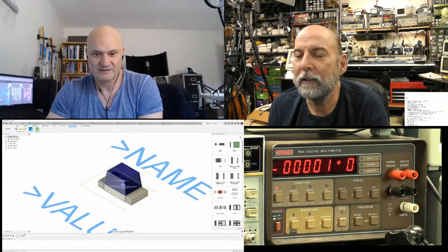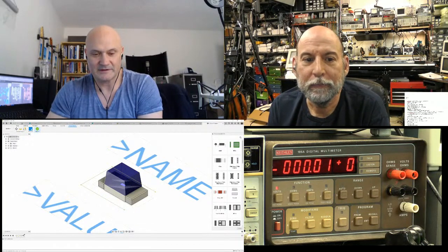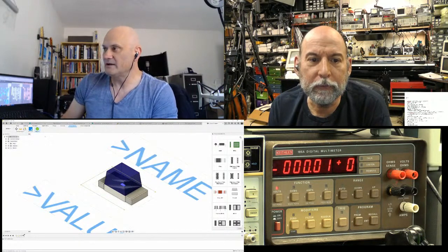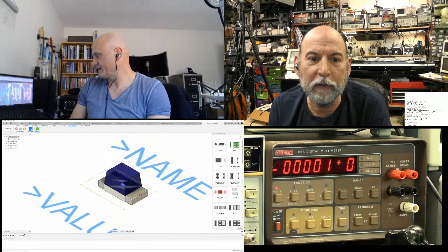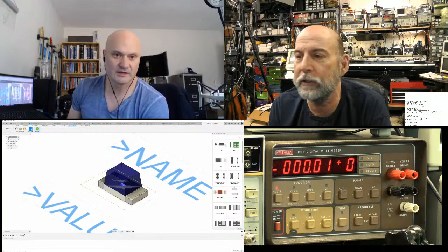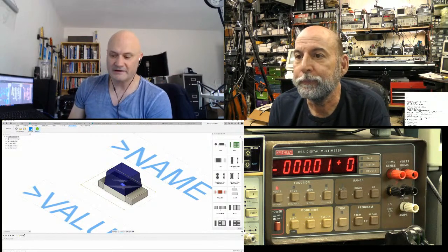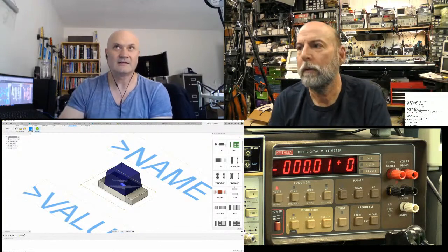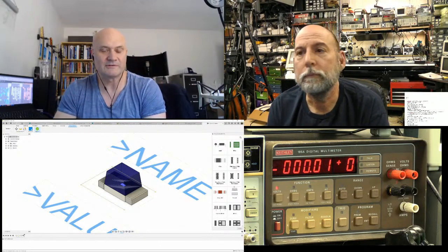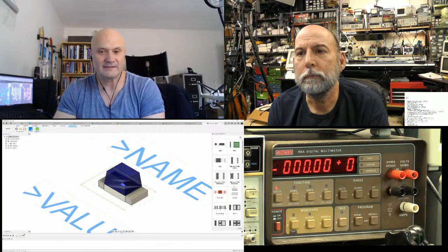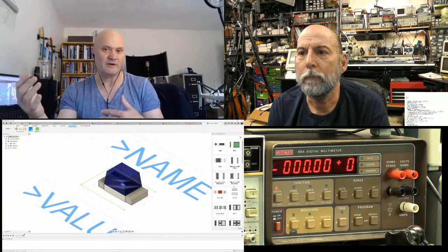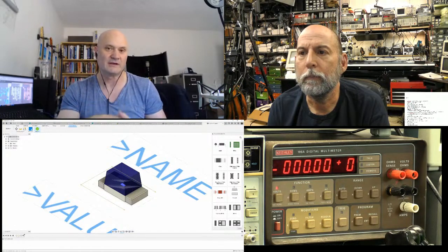Okay. Wow. So it's pretty powerful. I love it. Somebody's asking if you can import design files like Altium files. I can't import Altium into Fusion. Well, there's a ULP that will take Altium ASCII or PCAD ASCII. So technically a two-dimensional board file from Altium you can import.